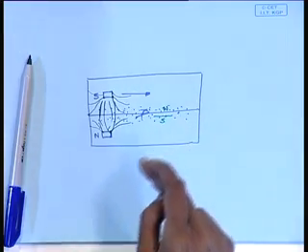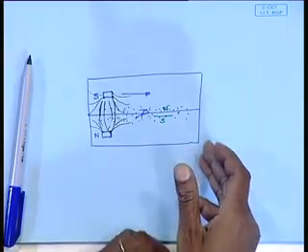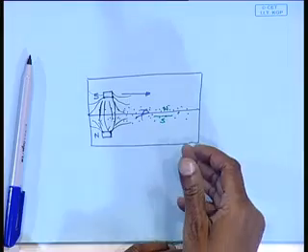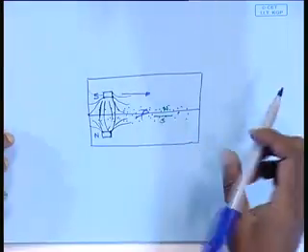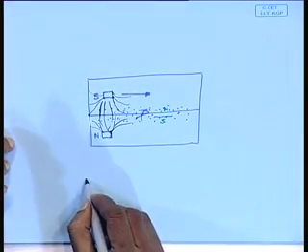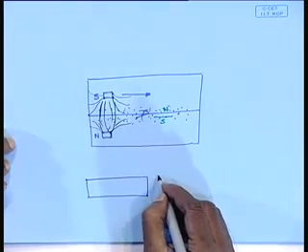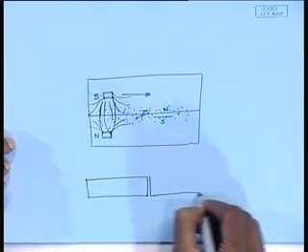And the second limitation is the welded material has to be magnetic. That means for aluminum welding I cannot use it. Third is it has a limitation in the penetrating power of the magnetic field.